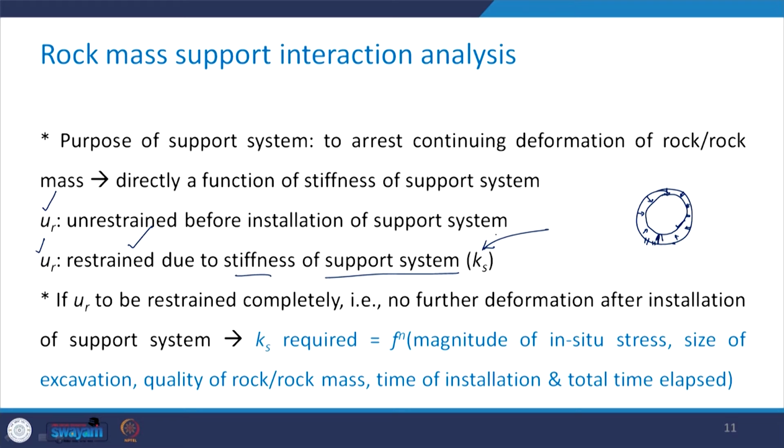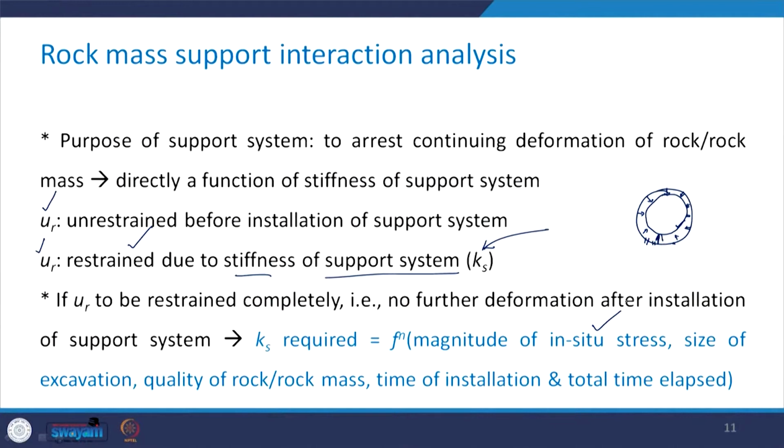Obviously, the stiffness of the support system Ks which is required will be quite high, and therefore the required Ks becomes a function of the magnitude of in situ stresses, size of the excavation, quality of the rock or rock mass, time of the support installation, and the total time that has elapsed.